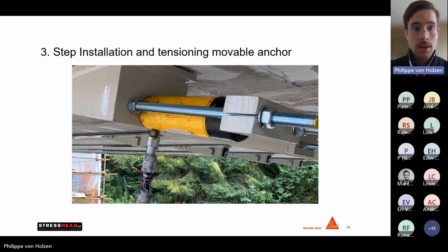Earlier, Eri mentioned already that we have no tensioning losses. We will see this at the end of the presentation in some tests, but I would like to show this here as well. We don't have the same fixation as we know from steel cables, with this slip behavior, as we really just tighten the knots. The whole force is in the structure and the threaded rods afterwards, there's no movement.